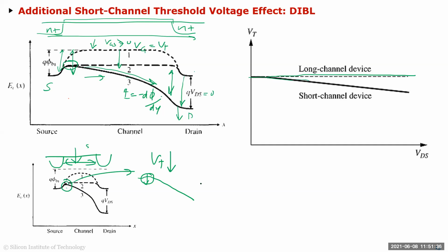When you're applying a voltage, essentially you're lowering the field, because your potential is the potential of a positron or a hole, you can say, which means that the electron potential is lower than that, right? So as you're increasing this voltage, applying a voltage here to the source, your positive potential goes up, which means that the electron potential goes down by the same amount, Q times VDS.